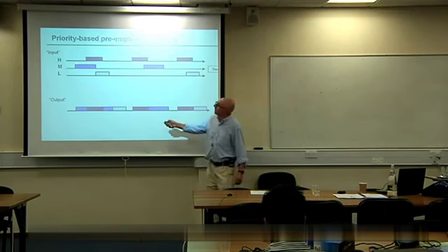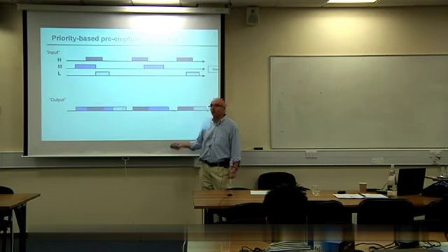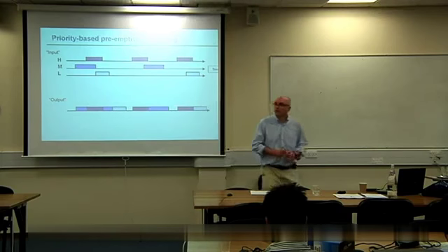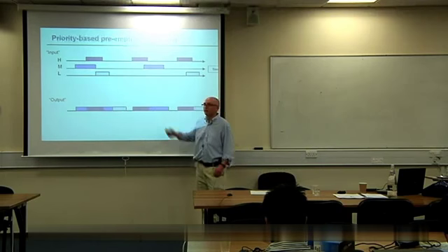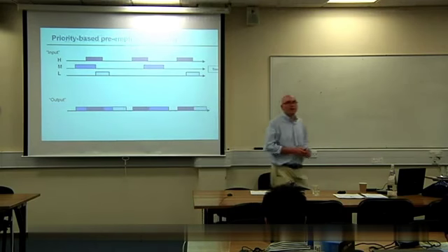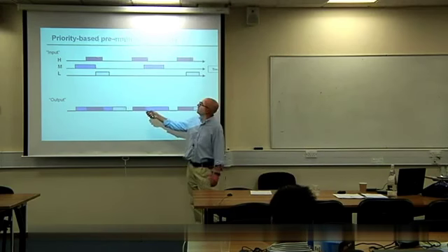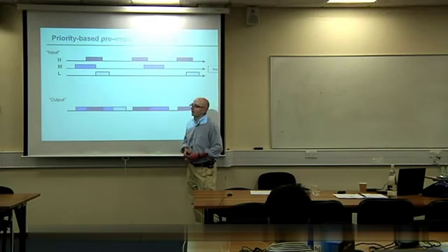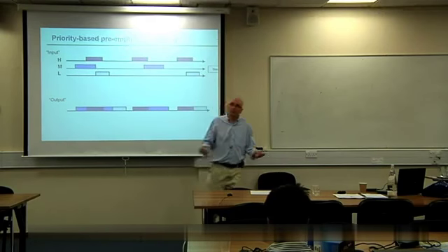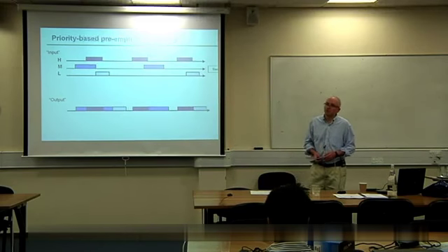Suppose this task, suppose it's not an ADC, suppose it's just an array of data that you're writing to. This task could be halfway through writing to that array of data. Then the higher priority task could interrupt. So the data is only half updated, some old, some new, and this task requires access to these data, and it uses data that may mean absolutely nothing and may be positively dangerous. What would you do in those circumstances?